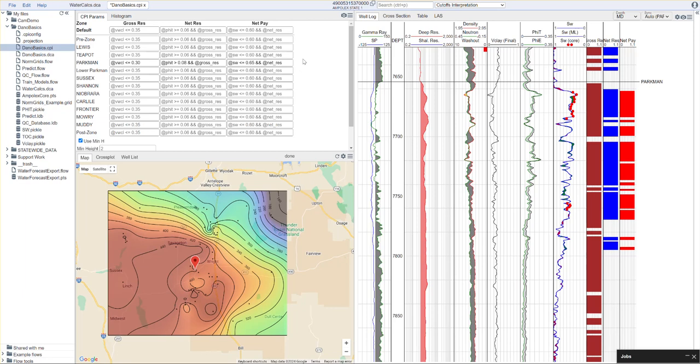Well, what we would want to do is look at our core data. So let's say, for example, we look at our relative permeability, and we say, all right, what is the water saturation that corresponds to our relative permeability of oil essentially going to zero? And what we'll see is that the rel perm of oil to water may occur at some value between 65 and 70% in this case, and that's where we're setting that up.